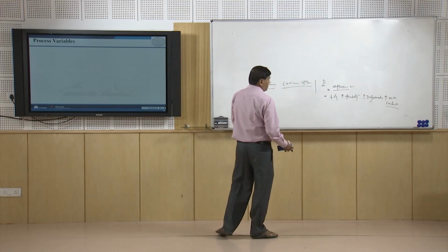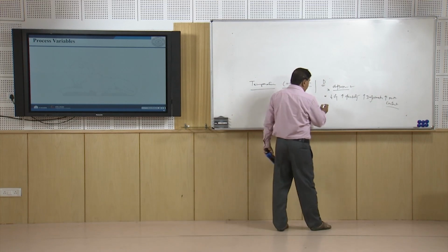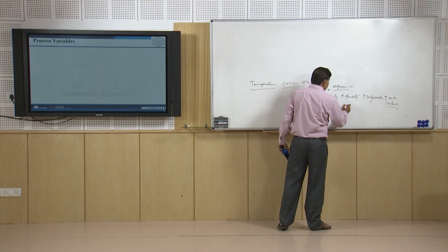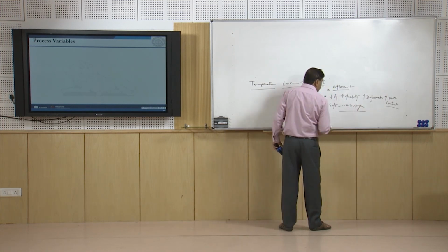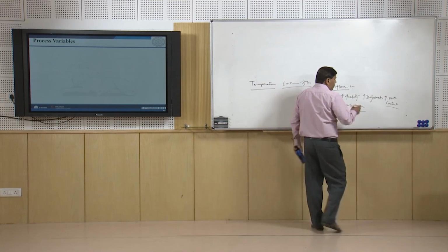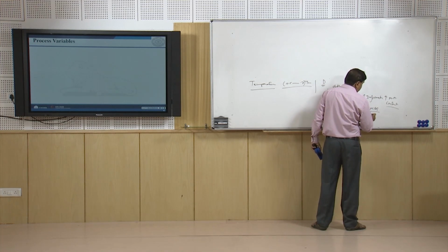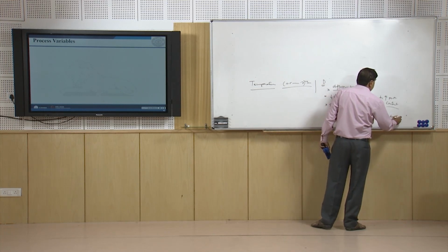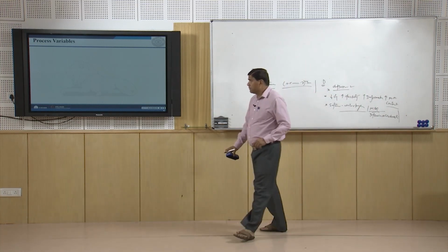It also helps to soften the interlayer if it is being used, to improve the metal to metal contact or to facilitate the diffusion. So, it can be used as a diffusion accelerator, or just to have better metal to metal connectivity between the members.